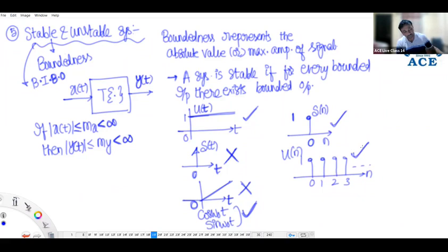That is wrong. Like we checked the linearity condition, stability is also linked to output amplitude versus input amplitude. A system is stable if for every bounded input there exists bounded output. Please go through it, everyone. We are using the word marginal stability, that is in the s-plane. When you learn control systems, what is the margin there? j omega axis is the margin. In the time domain, there is no margin, sir. Time domain stability is BIBO, bounded input, bounded output.